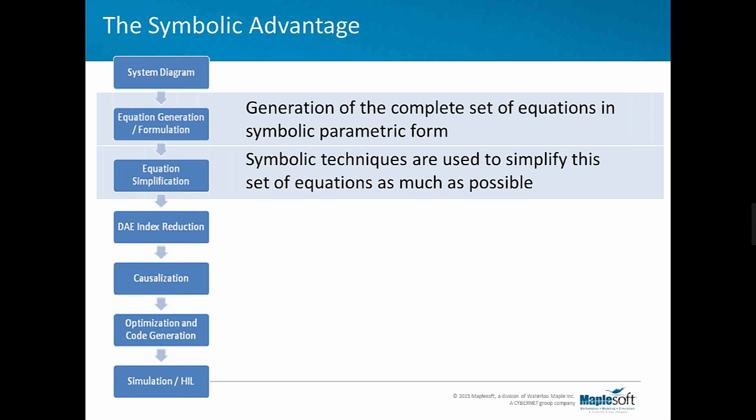Other steps that can be done when you have a symbolic computation tool at your disposal include operations such as a zero multiplied by a large expression. You can save on not evaluating the expression by evaluating the multiplication symbolically and substituting zero for that large expression. Matrix manipulations and trigonometric manipulations are all in the realm of symbolic computation that we perform on the equations generated from MapleSim inside the Maple engine.